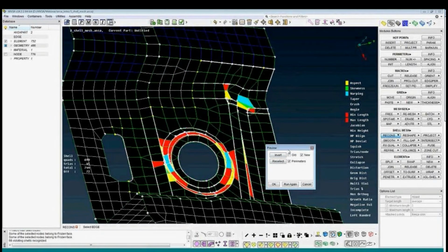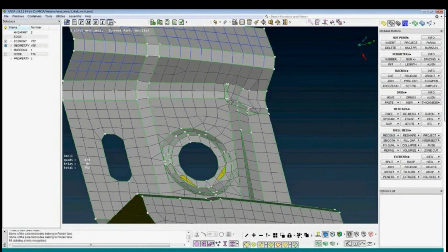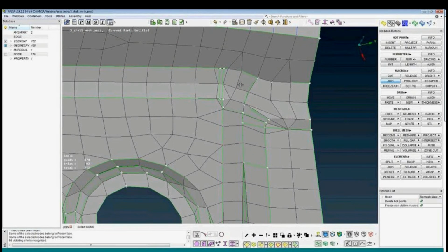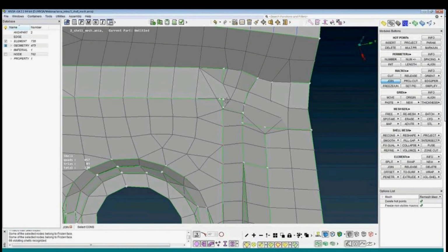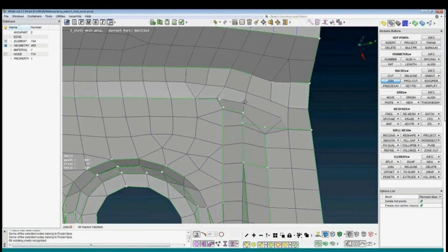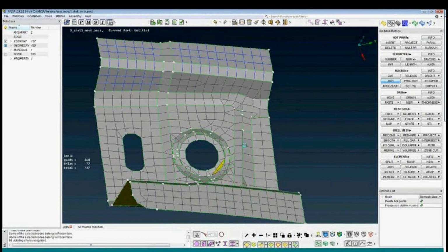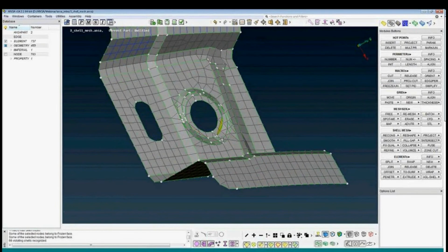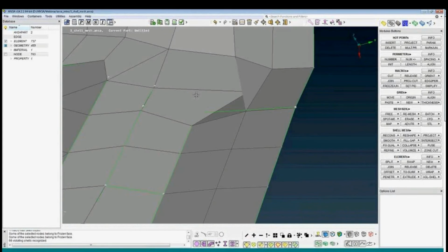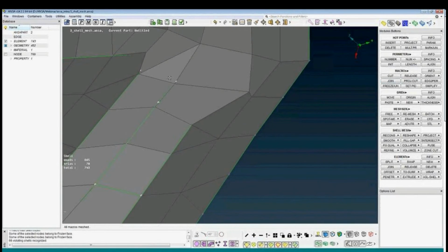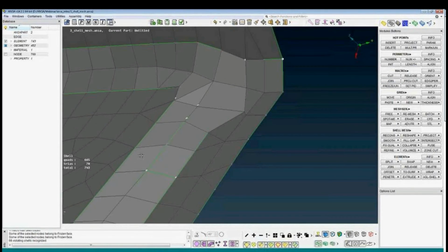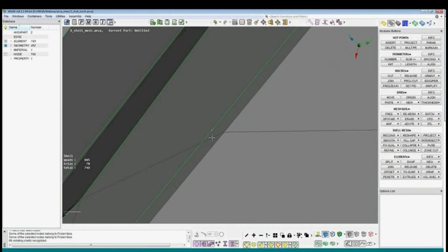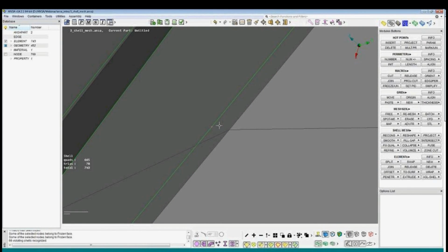Okay, this was a hard geometry to reconstruct because there are too many small faces. So I can join some of them. Also, what you notice is that now the elements are moved from the surface. We have a distance between a node and the geometry. And this is the parameter that we set: 5% of element length is okay to move the node from geometry to fulfill the criteria.